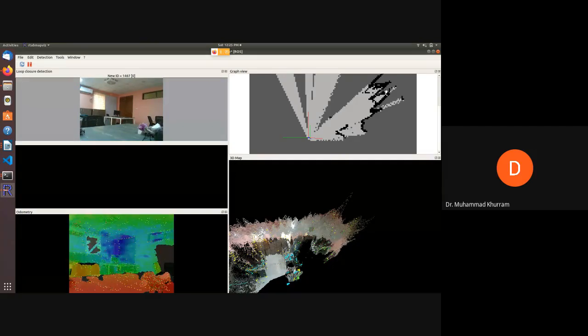So this is how we are creating a 2D occupancy grid. In an occupancy grid, there is no information about a dynamic object. You might have seen that on this black screen, in the middle of top left and bottom, there were some visuals of dynamic objects coming and going. These visuals were actually being utilized to identify the dynamic nature of the environment, and the values were being used to eliminate those dynamic elements from the map. That is how we create a 2D static environment for a vehicle.